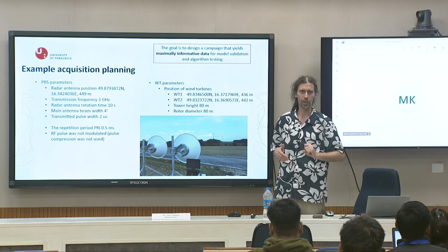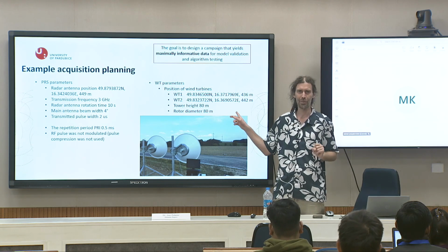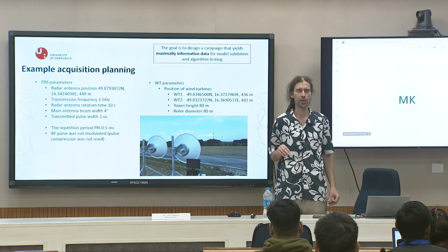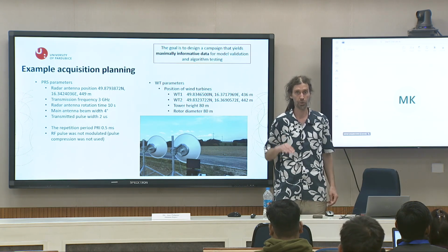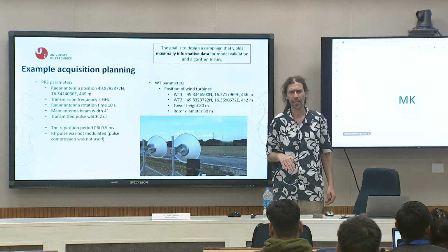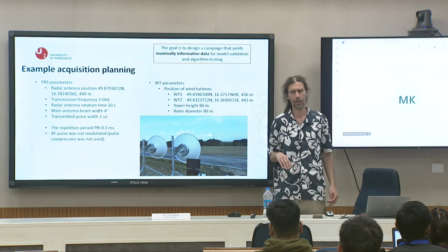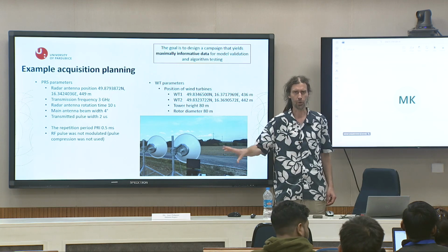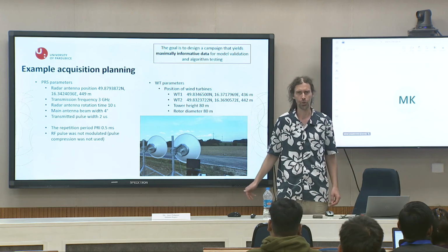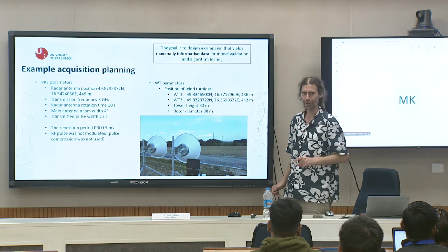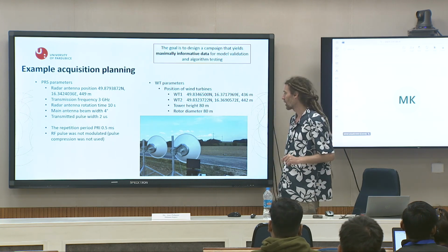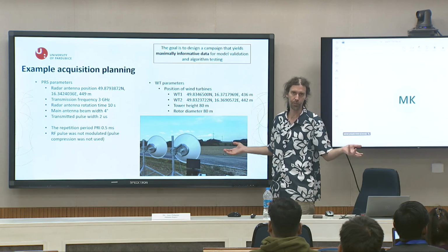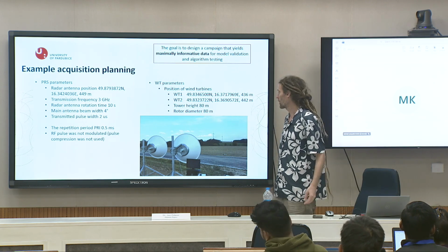So back to your question, we just adjusted this 40 megahertz related to the cache memory of our SDR, because if we put 50, 60 megahertz, because we also want more, the SDR can't handle such high data rate, and always after a few seconds of record it causes a problem, overflowing and shutdown. So I remember now it was about this SDR cache memory. But it depends on your devices. If you have better devices or a real radar, it will be something else, of course.